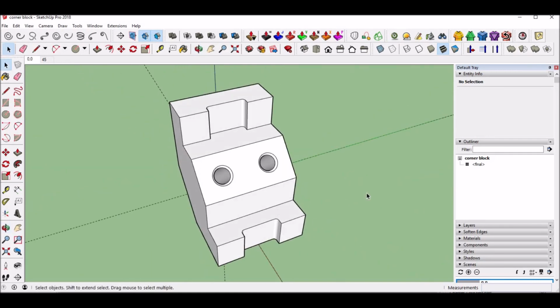But anyway, that's how you do mass evaluation with SketchUp. It's not as nifty as other programs that automatically do it, but I'd love to be able to program an extension that will do it. But for right now, that Excel sheet is perfect.